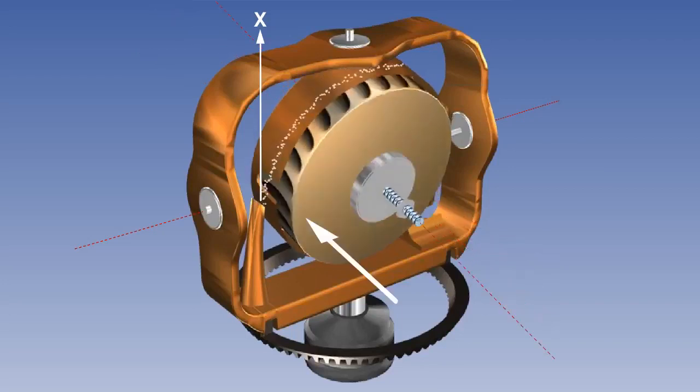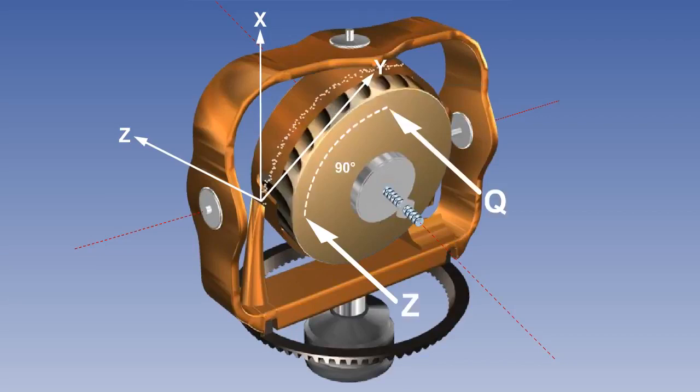If the gyro topples but the aircraft stays level, the rotor is no longer in the yawing plane of the aircraft, or at right angles to the outer gimbal axis. As the air jet is fixed to the outer gimbal, the airstream now strikes the rotor at an angle. The resulting force can be resolved into 2 components, Y and Z. Component Z will precess the rotor as if the force had been applied at a point 90 degrees around the circumference of the rotor in the direction of spin at position Q. The effect is therefore to realign the rotor with its axis in the yawing plane.